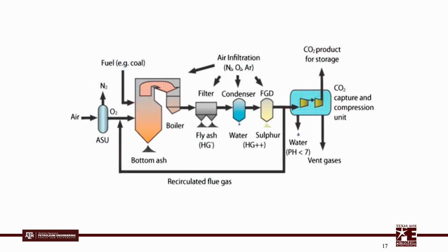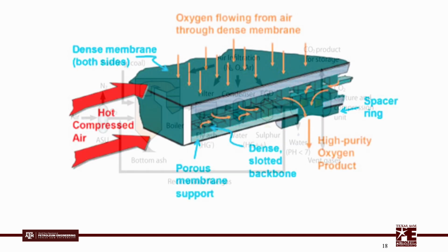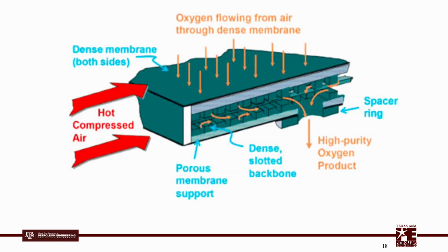One technology that has been in development that could greatly assist in improving the efficiency of oxy-fuel combustion as well as integrated gasification combined cycle-based carbon capture is ion transport membrane technology. This technology is a membrane system for the capture of oxygen rather than carbon dioxide. This process, if successful, has the potential to replace traditional ASU systems in producing oxygen.